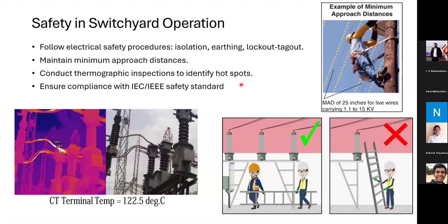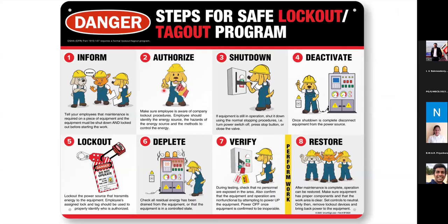And remotely, without going in, you can do thermographic inspections to identify hotspots and detect any abnormal conditions like this. And you need to ensure that working in these switchyards complies with IEC or IEEE safety standards.